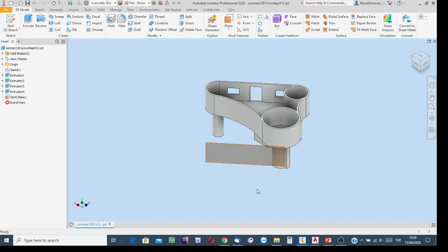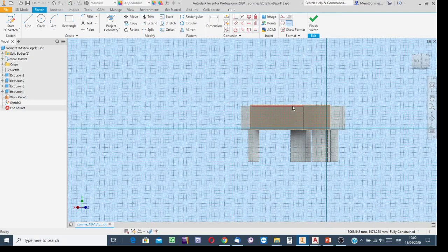It is imaginary, but since it is flat, we can take a sketch right on it. Indicate it with a click, bring the cursor to its boundary, right click the mouse and say new sketch. Over the curved surface it is impossible to start the sketching stage, but over that flat surface, yes. That's why I had such a flat surface. And then the rest: create the circle, because over that surface we need to create such an empty space.